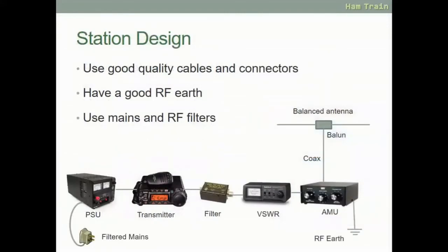So, a station design then. Use good quality cables and connectors. Try not to buy the really cheap stuff. Use the best quality you can afford to actually put your station together. If you can, have a good RF earth, and use mains and RF filters wherever you can.